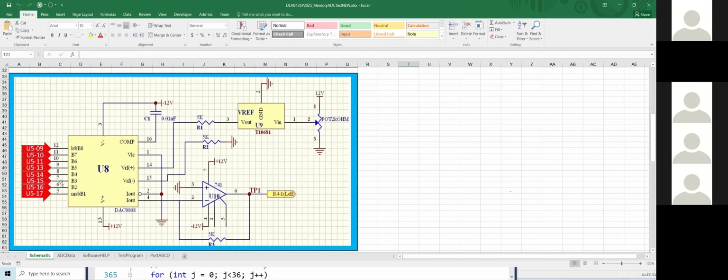However, they convert into the output current, I out, pin number 4. And basically, after you build this circuitry, they already tell you to connect the meter to U9 pin 3 and adjust the port here until you get 10 volts.